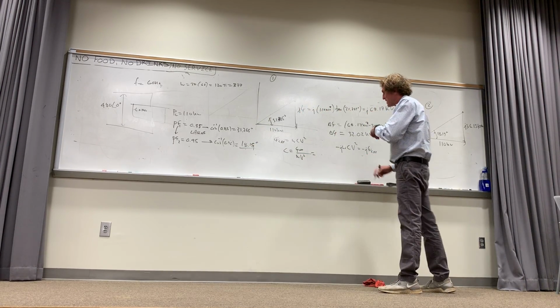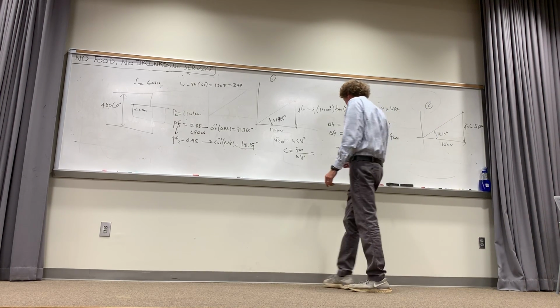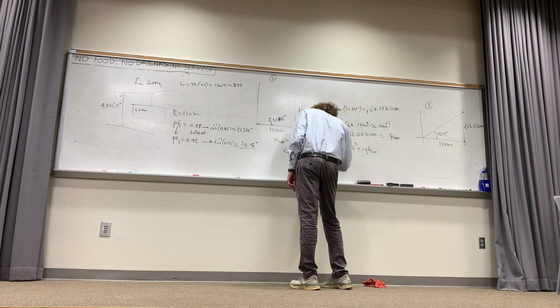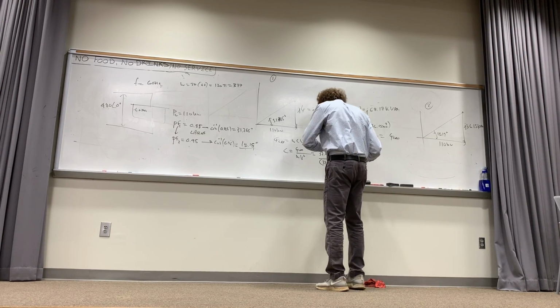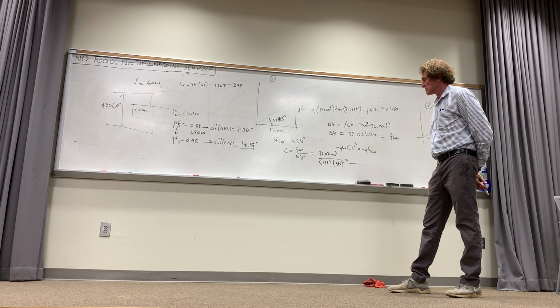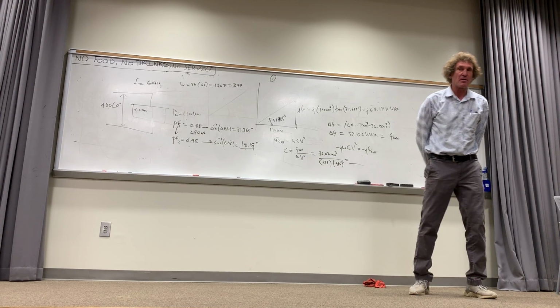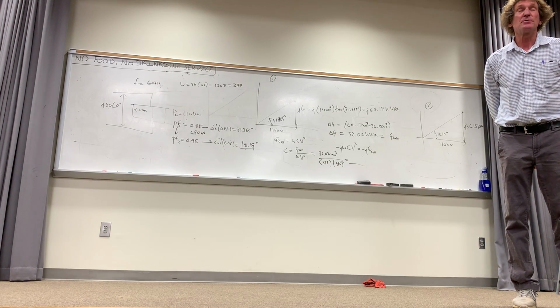Now for our problem, the delta Q that we had was 32.02 times 10 to the third. Omega was 377. Now the voltage is 480, and you square that and you're going to get a single value there. Can you give me that value? Is that Q cap equals omega C V squared? Sure. It's just the capacitor's complex power. I got rid of the j's because sometimes they're just distracting. That's the Q, its reactive power.